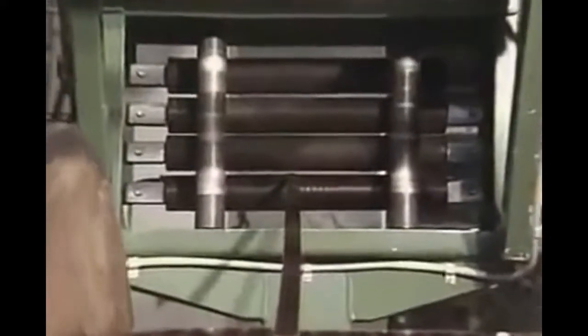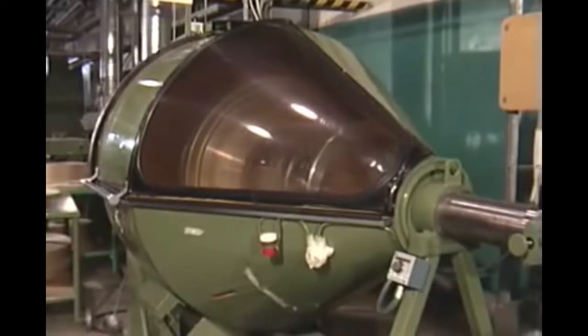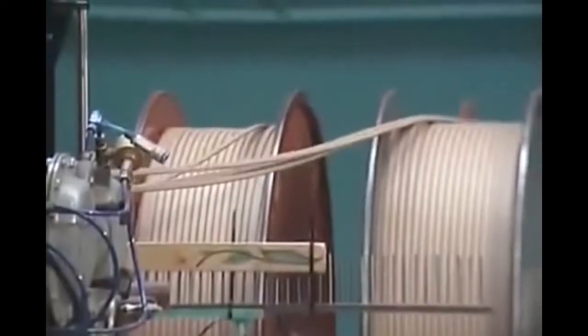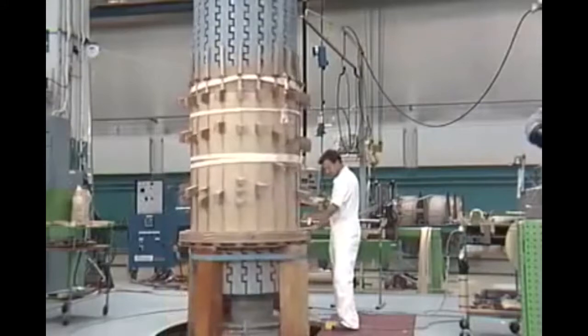The construction of the windings illustrates once again ABB's attention to detail and quality, as well as the flexibility of our manufacturing operations. High-quality insulated electrolytic copper conductors wrapped in special insulating paper are used for the windings. The exact choice of conductor and winding configuration is made on the basis of ABB's vast wealth of experience. It takes into account an array of factors, such as economy and loss expectation, as well as dielectric and mechanical